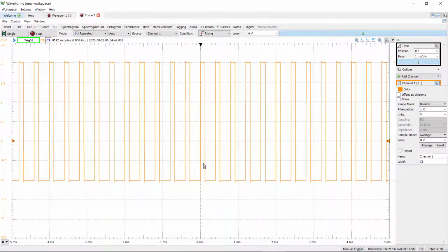Now let's take a look at our square wave. We're at 1 millisecond per division. We've got 1 cycle, 2 cycles, and a little bit more, so it's a little bit more than 2 cycles per division. So it's about 2 kilohertz as the frequency. The duty cycle we can see here is a little distorted. So we have a rough idea of what to expect in the signal.